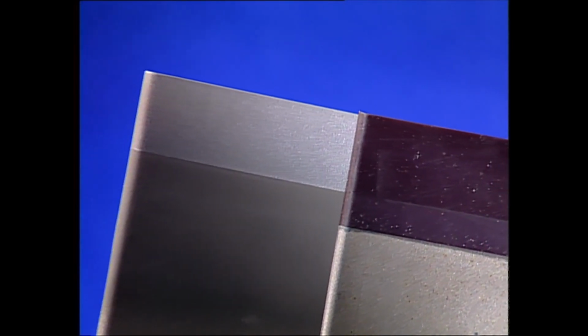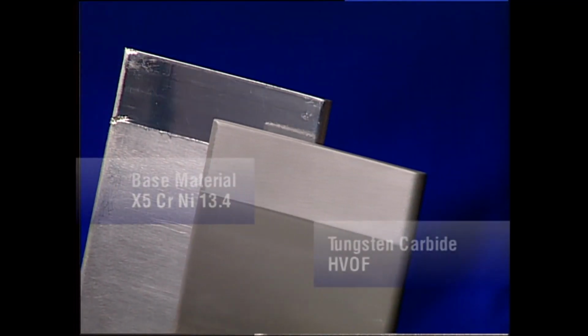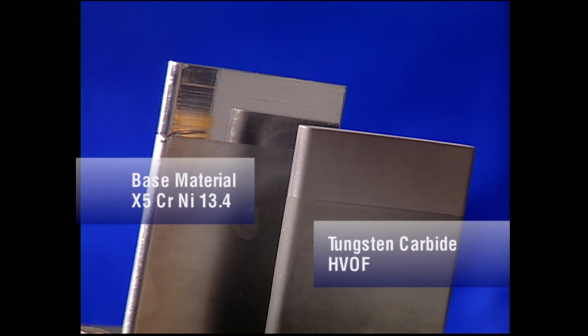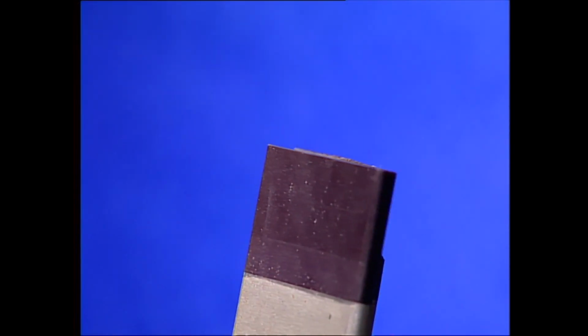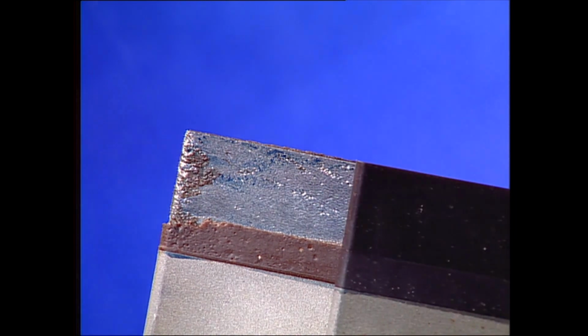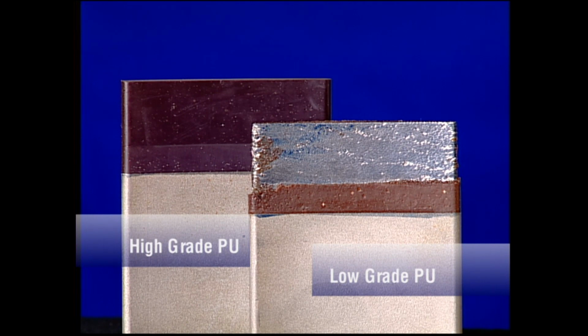The results essentially confirm the ranking which was found in the slurry pot test. Thermally sprayed hard coatings based on tungsten carbide have resulted in superior erosion resistance compared to the base material. Excellent results were also found with the high-performance polyurethane materials. Again, the tests confirmed significant differences within the class of polymer materials.